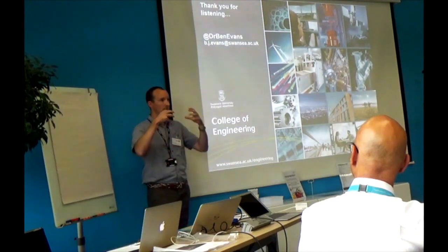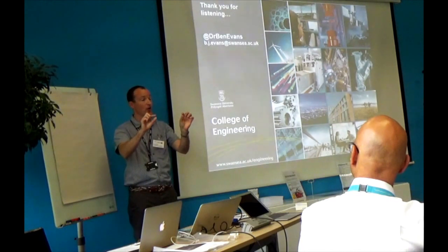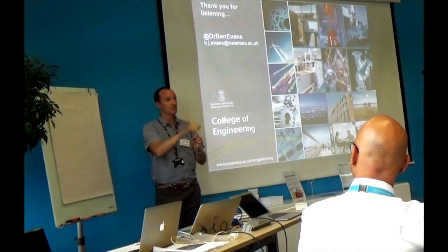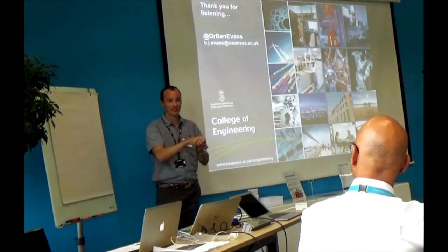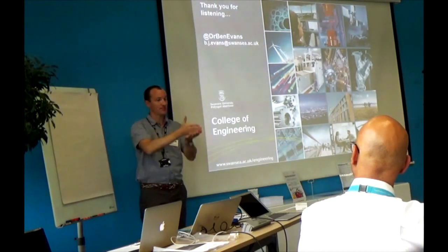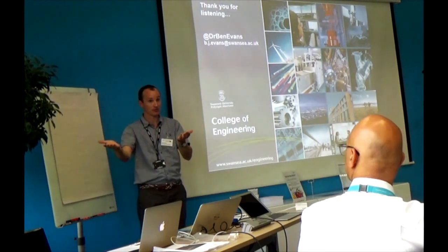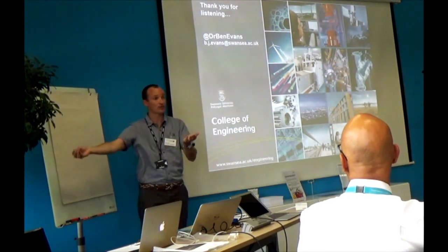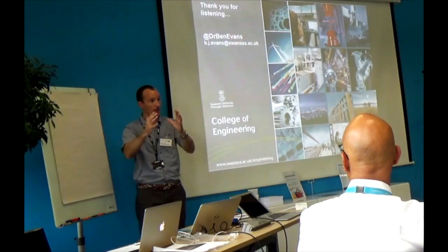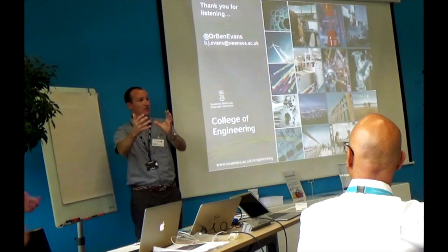Now, someone with experience and intuition can look at that and go, okay, aerodynamics, I can understand why you're clustering here. Or you can look at degrees of freedom that don't seem to be very sensitive. So you could say, well, there doesn't seem to be any clustering on this particular degree of freedom, which potentially implies that degree of freedom isn't important. So maybe we can take that out of the design space, make the design space smaller, and help the optimizer find the optimum of the other degrees of freedom.